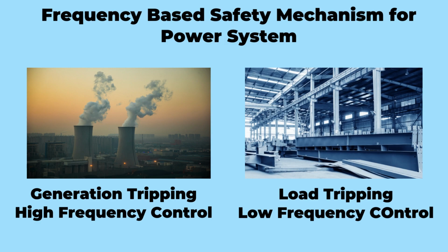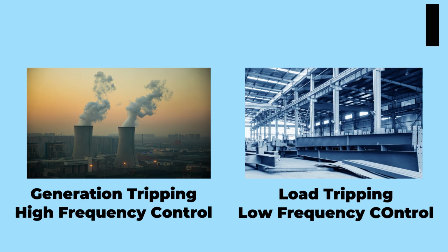Considering the detrimental effects of significant frequency variations on the power system, various safety measures are in place. Some grids implement stage-wise generator and load tripping mechanisms, designed to control high-frequency and low-frequency deviations respectively. These measures help maintain system stability and protect both the generators and the interconnected equipment. By setting limits and enabling frequency-related tripping, power systems with synchronous generators can better safeguard against significant frequency variations. These protective measures ensure the reliability and longevity of the power system, preventing potential damage and disruptions.